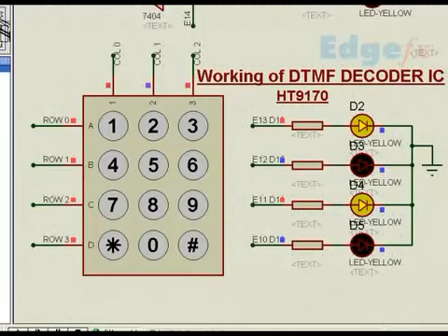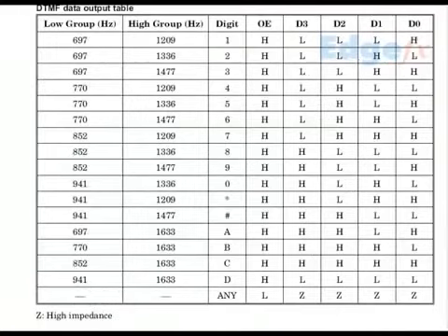This is how the IVRS, the interactive voice response system, also works, where the tone is converted to the particular number in binary. This table is universal throughout the world, and that is why anywhere we use any number, these are the frequencies at which the dual tone is generated, and the tone decoder decodes it. There is an arrangement for a tone encoder also. We will discuss that separately in the tone encoder section.